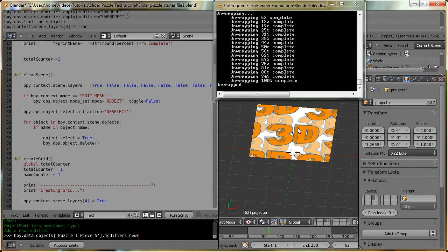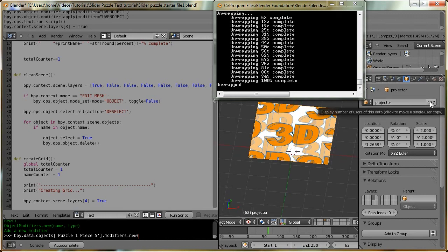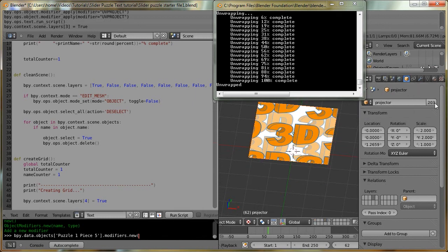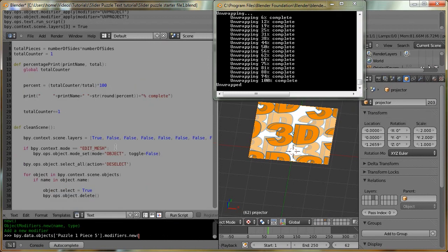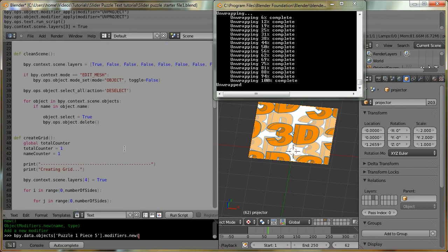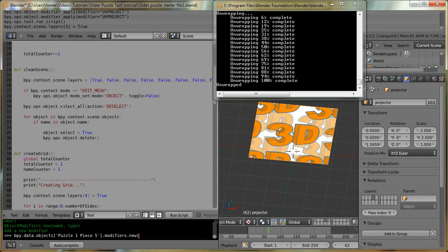So even though we've only got 16 objects, it's saying it's being used by 187 objects, because each time we run our script, more are getting added, even though those objects are technically deleted. And that's because Blender won't get rid of those users until the file is reloaded. So what we can do is actually clear out the users for it each time we run the script.